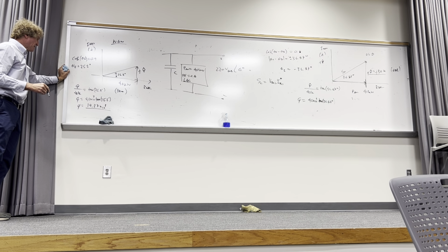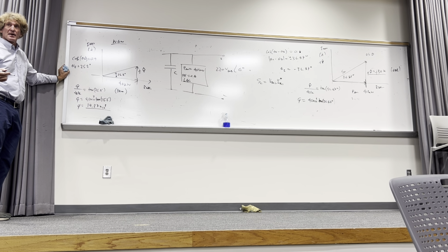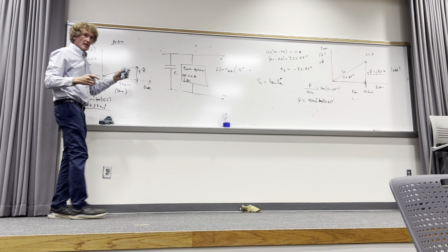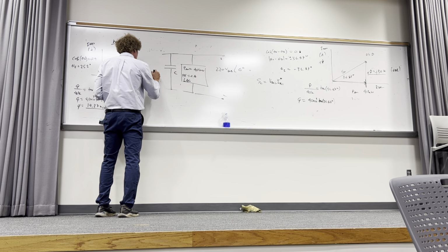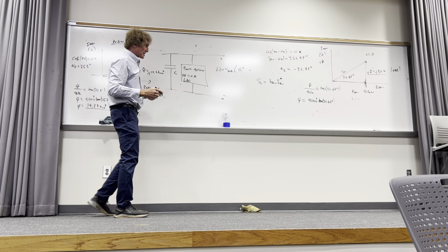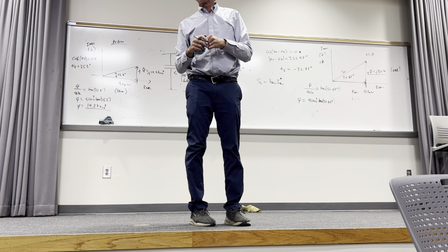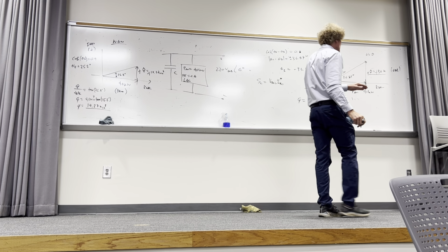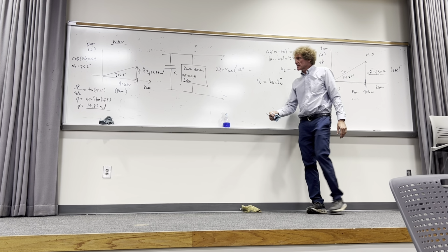All right, 19.37 kVAR. Pardon me? Is that right? How many got that? Just help me out here. Okay. So I know this value, right? I'll go ahead and put down J19.37. I'll just put times 10 to the third, so you don't get a mistake. I hope you can all read that. Now, where did that come from is the next obvious question. Well, I started with this, J30K, right? When I added the capacitor, it went down to this value, right?